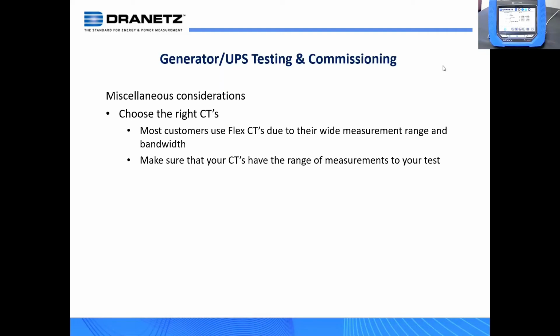Oftentimes to key in on the battery level, the benefit of any of our products, our fixed products or our portables, is we have differential inputs. We also have that spare D channel or neutral channel. A lot of times they wrap that around and measure the internal battery of a UPS.